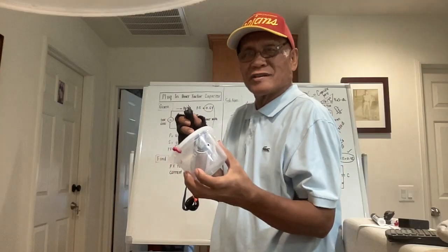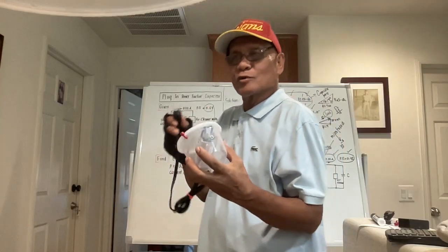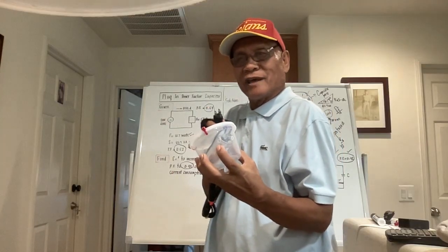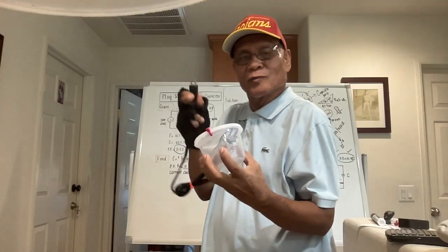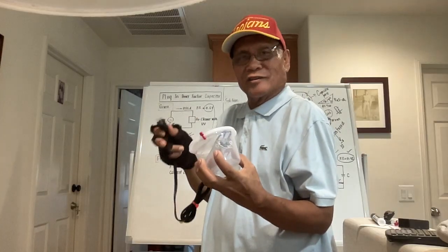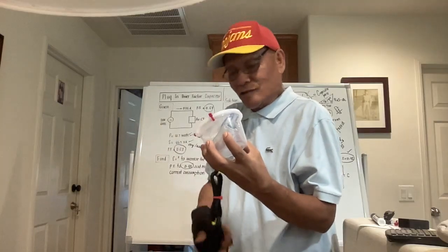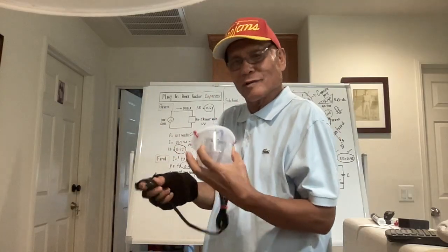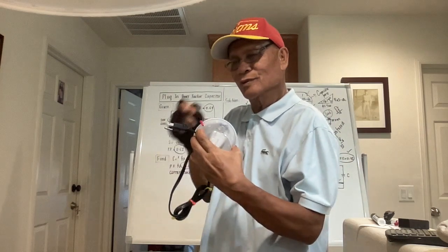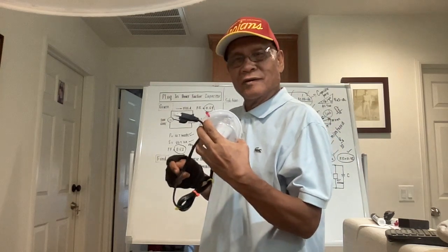Okay, assuming there is a voltage stored on the capacitor of 120, but I put a load across it of 1 million ohms, that current is very small, and it keeps circulating till the charge on the terminal will be 0. So this one now will be safe to touch.